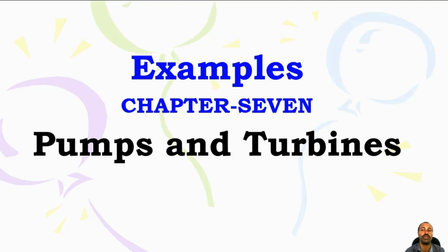Positive displacement pumps consist of ram, piston, and also valve arrangement. You have, for example, reciprocating pumps and rotary pumps. And rotordynamic pumps rely on rotational movement for their pumping action. It relies on rotational movement by the help of an impeller. Examples, we can take centrifugal pumps, axial flow pumps, and mixed flow pumps.